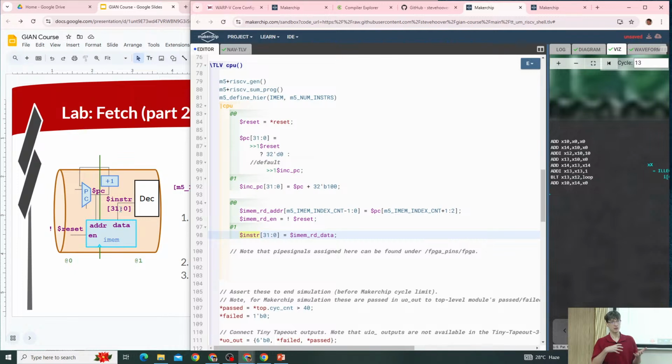But the actual computation that's performed in the transaction, so basically the microarchitecture tends to be composed of the transactions and the logic that's acting on the transactions and the microarchitectural state that's updated by those transactions. So the transaction marches along through the machinery. In our case, it's a simple pipeline. We fetch the instruction. That's our transaction. It's going to march through the CPU pipeline. And as it marches along, it's going to update microarchitectural state, things like the register values or writes to memory. Where you have microarchitectural state that carries over from one instruction to the next, that's where you need to make sure that you're not updating that state for invalid instructions. But we will tend to cut off things at that point, at the state.